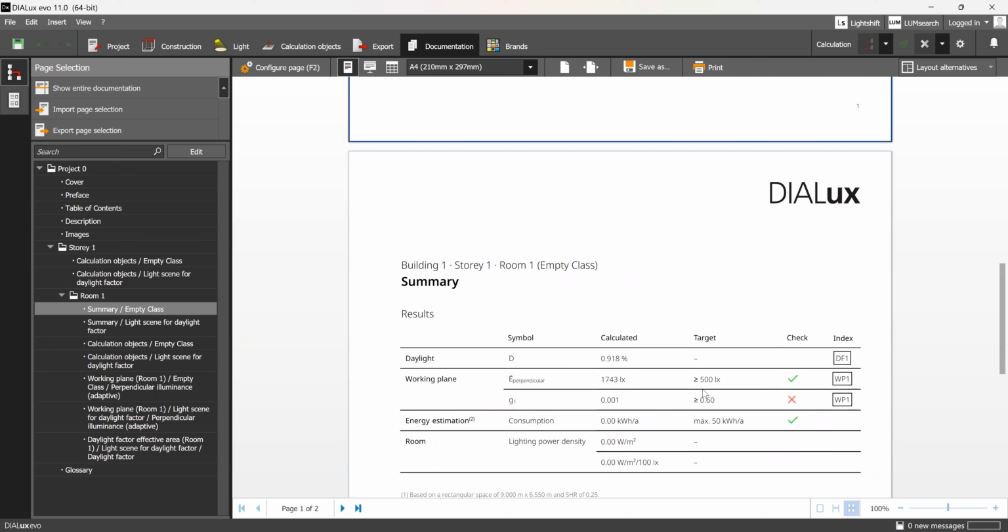Now, what was the impact of the blind? A roller blind, one of those that we have in most of our rooms, closing it completely means you are creating a very dark space, which is useless. What might be helpful at some point is to block some excessive light. Right now, we left 25% open. Probably if we left the whole thing open, the external one, it was probably going about 2000. You can give it a try later on as well. Right now, it is passing the bare minimums, and you can see how it is happening.